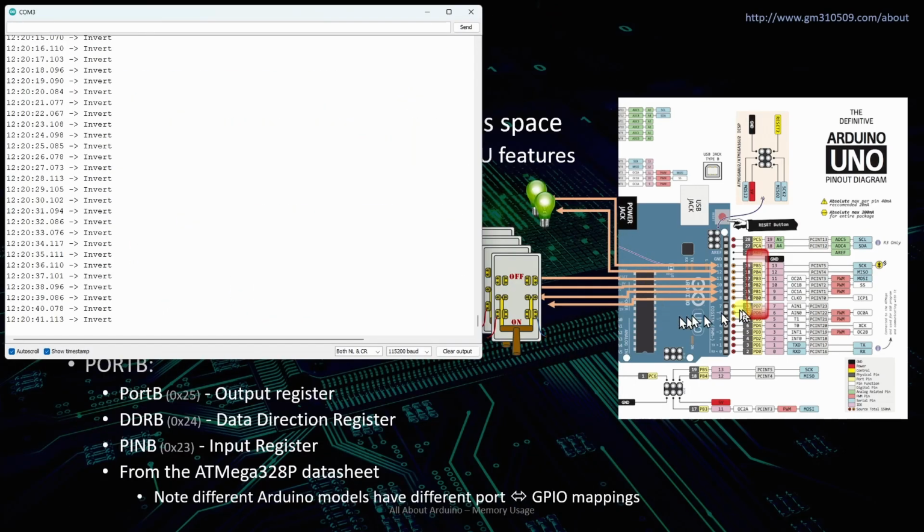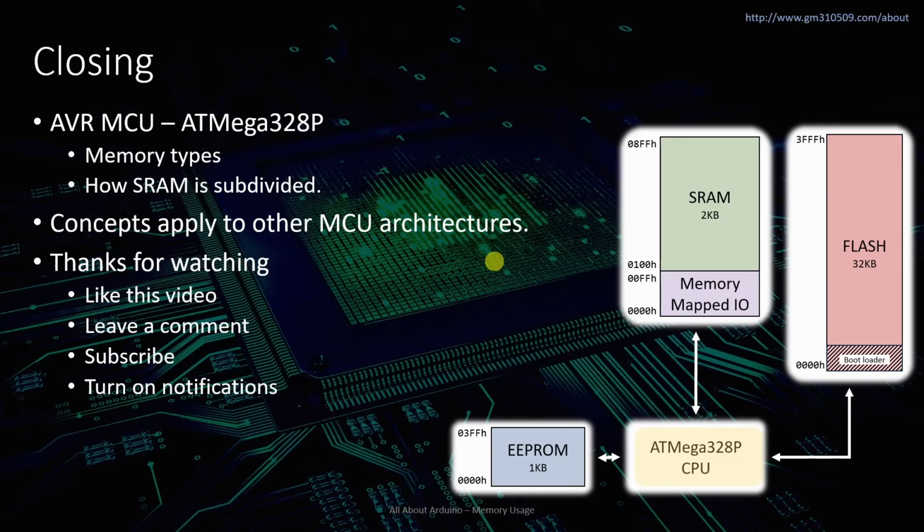So hopefully that was interesting, and gives you a bit of an insight into how the I/O works on the MCU. They're not all the same, but generally there's a memory-mapped I/O capability, and you can just use regular random access memory instructions to read the values from these connections into your code, which is running on this chip. So hopefully that was informative.